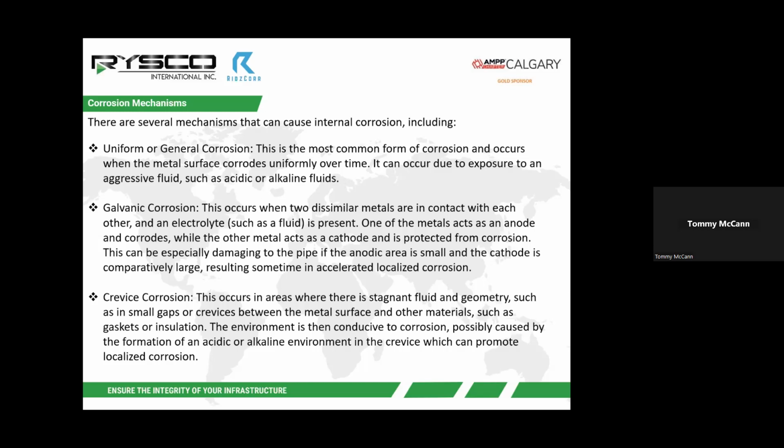Galvanic corrosion, so this is something that everyone has to be very aware of. We have different potential for dissimilar metals contacting each other, and where you have that electrolyte, commonly a fluid, one of the materials will be the anode, which will corrode, because the other will be the cathode, and that one is usually protected from corrosion. Can be very damaging to the pipe if the anodic area is small and the cathode is large. That can also cause some fairly accelerated localized corrosion.